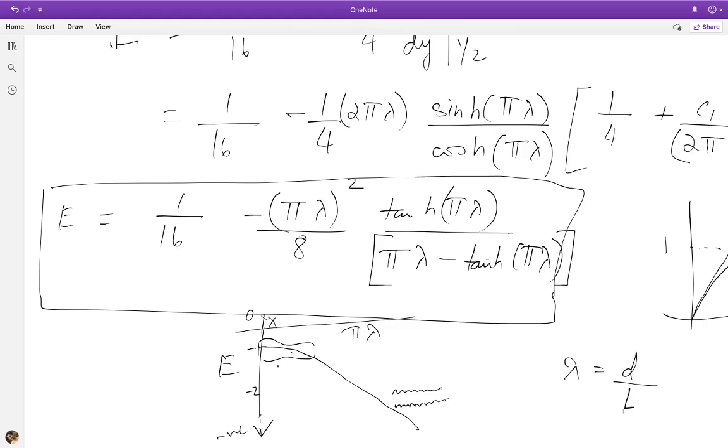So for the same applied pressure gradient, if epsilon is 0, I have only unidirectional flow. On the other hand, if epsilon is finite, the same applied pressure gradient has to drive not only the flow in the x direction, but also the flow in the y direction. So the added component of velocity in the y direction basically is coming at the cost of the x directional flow. From an energy perspective, the fact that you now have gradients in the flow in the x direction as well as in y means my viscous dissipation is going to increase. And so from an energetic perspective, I'm losing more energy to viscous dissipation, and consequently the total flow rate I get of the problem is reduced.